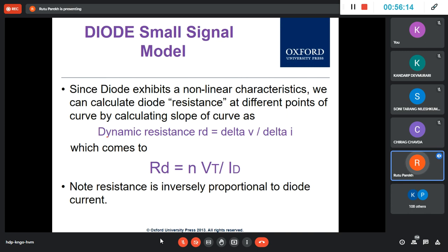So now you know that the diode curve is exponential, it is not linear. And as I said, in the piecewise linear model, RD will remain the same, but in the real exponential curve, your RD is changing, and hence we say it is a dynamic resistance. And it changes as per the voltage, as you can visualize now.